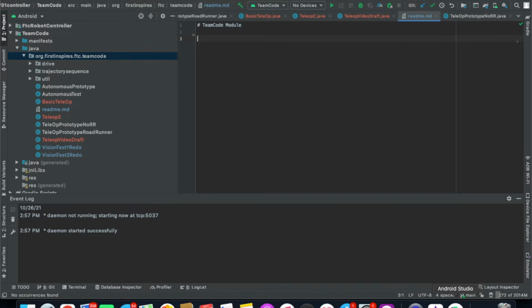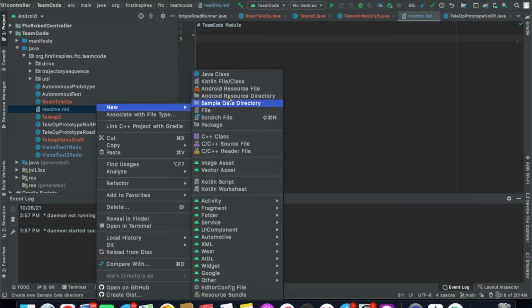In this video, we will walk through the steps to write a basic TeleOp program. TeleOp modes are used during the driver-controlled and endgame portions of an FTC match. The main purpose of this type of program is to match button inputs on a controller or gamepad to motors, servos, and other outputs. To start, create a new Java class in Android Studio.